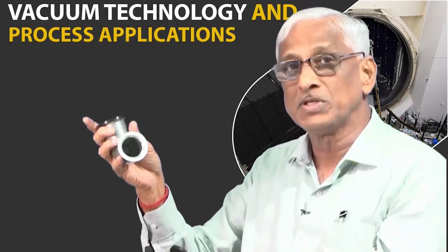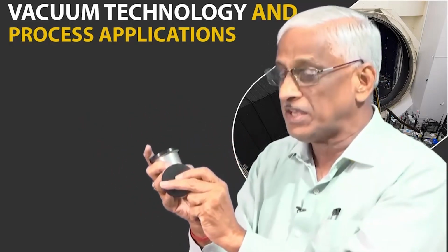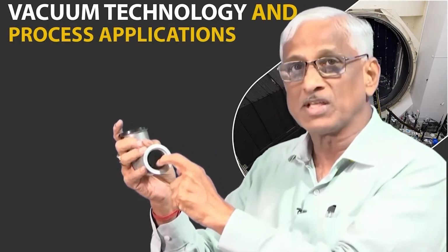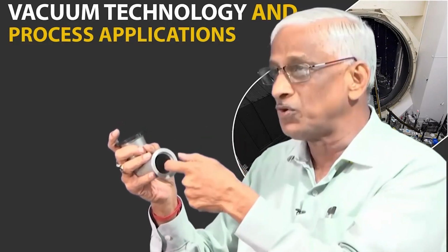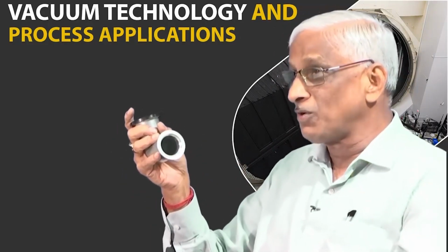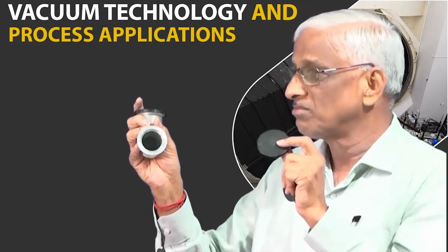And when you are not using this, you should close it with a plastic cup. Otherwise, if a small ant or something has gone in, and if it is dead inside and some fluids come out, at 10 power minus 5 torr, minus 6 torr, it will produce an enormous amount of gas and you will never get vacuum.